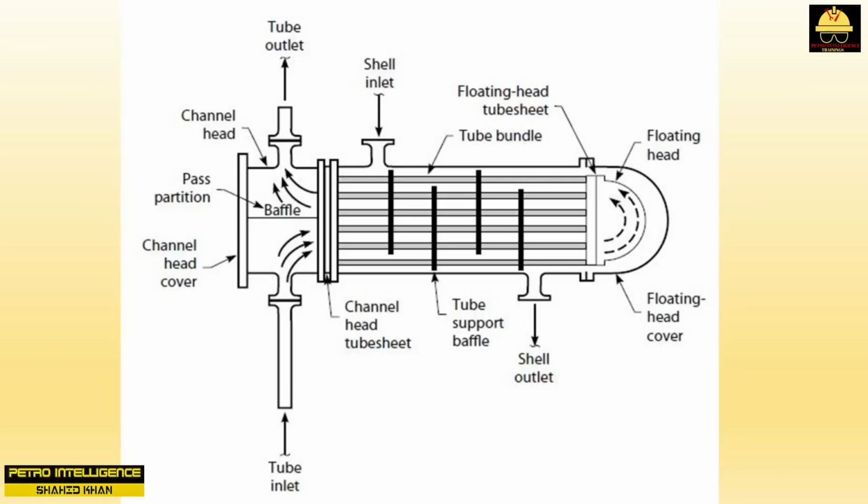The 4 tube support baffles shown in this exchanger as shown in picture serve a dual function. They serve to support the tubes. More importantly, they promote high crossflow velocity. The concept of crossflow velocity is quite important in understanding how heat exchangers work. This concept is related to a flow phenomenon called vortex shedding.